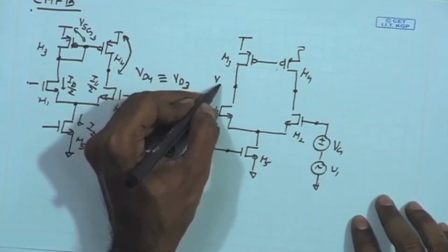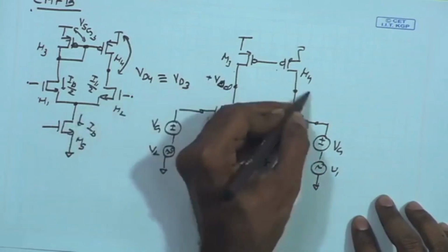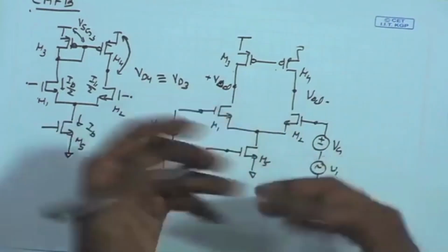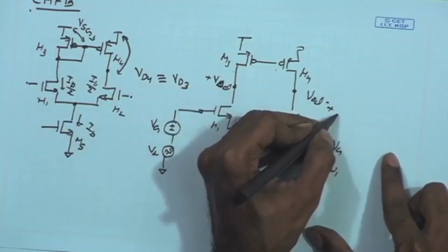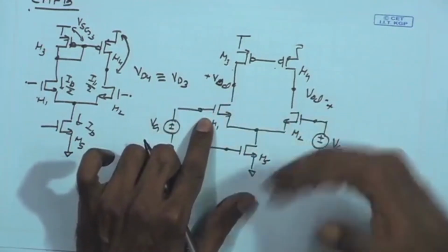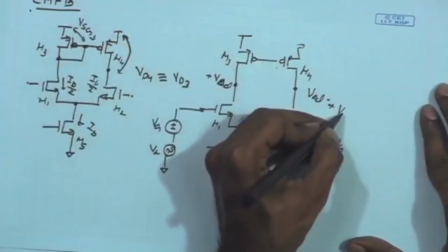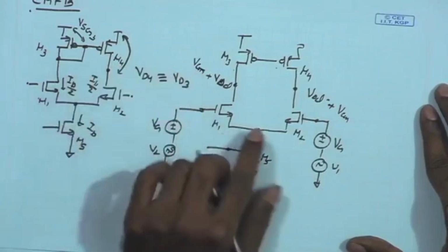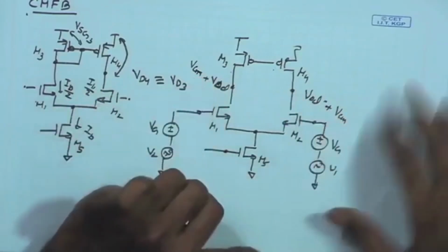so call it VOD plus and VOD minus. So, you will have some differential signal coming over here, and if I want to get the common mode signal, you have VOD plus the common mode level. It can also have DC plus AC. As I said, if the common mode gain is sufficient, it can also lead to some common mode signal over here. So, it may not be just a DC, it can be some common mode signal VCM plus VCM. So, assume that not only DC, but you also have a common mode AC signal.